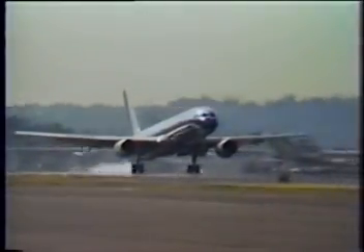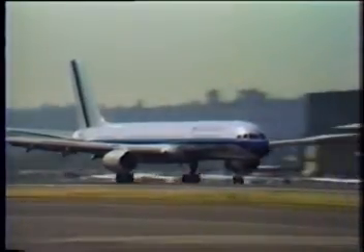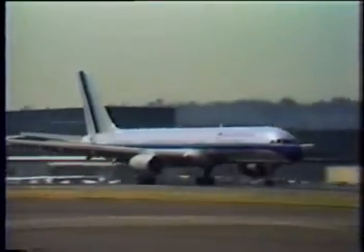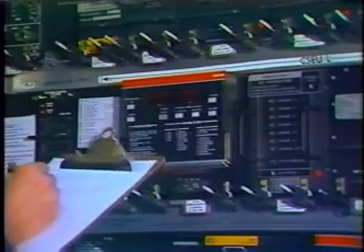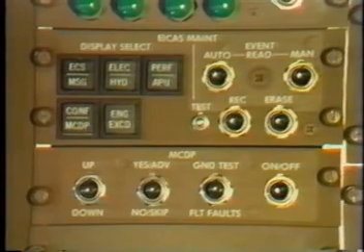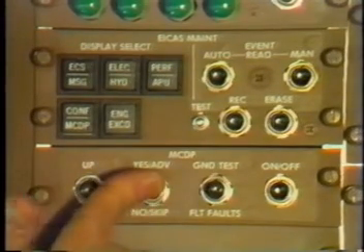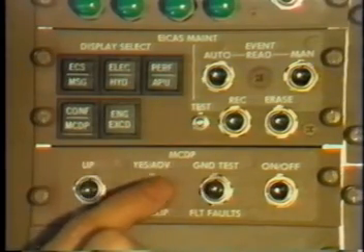The MCDP powers up at touchdown and stores faults which occurred during the last flight. Fault data retrieval and ground testing can be accomplished at the MCDP or from a remote panel in the flight compartment. Post-maintenance verification and Autoland confidence tests provide for systems integrity prior to dispatch.